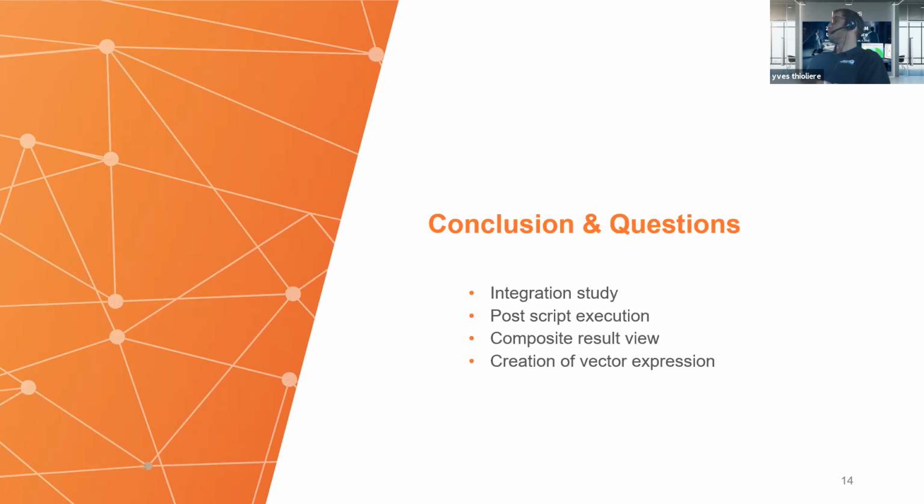It also depends on the accuracy you want in the efficiency map and which assumption and which tool you are using: speed priority, accuracy priority, or lumped element, or whether you are taking into account the numerical correction, which is just numerical, not FEA. So it depends on how fast you would like to achieve your map and which assumptions you are ready to consider.